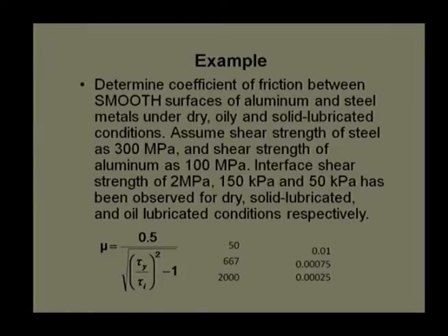I can interpret these results in three ways. First, dry contact gives a higher coefficient of friction. Second, getting a coefficient of friction equal to 0.00075 does not mean much; it will not really waste much power. So, these are hypothetical values. Third, as the coefficient of friction is very low, I can choose even the dry contact.